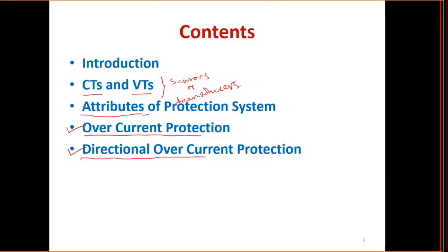But what is the purpose of the directional overcurrent relay? It will sense only in one direction. It will not sense in both directions, because it has some drawback if it senses in both directions.